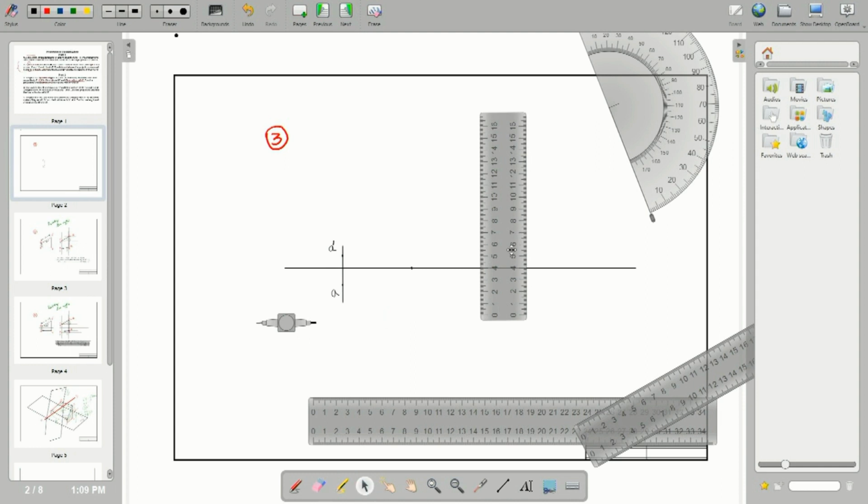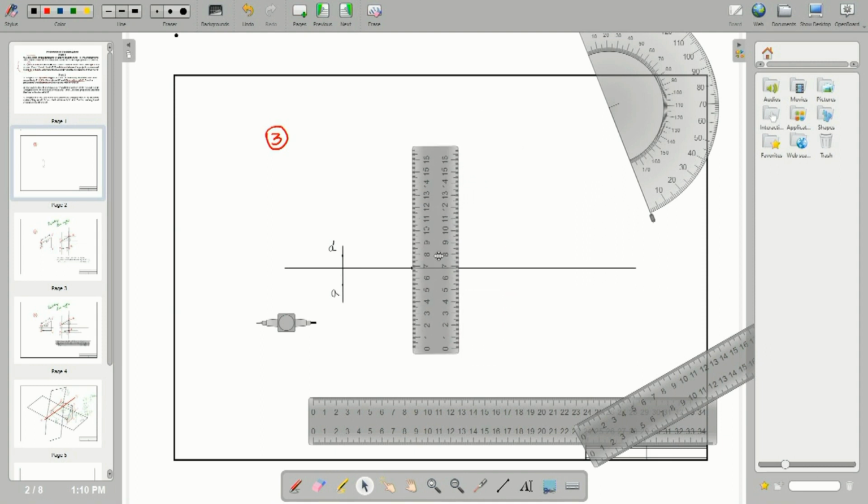By using perpendicular scales, that is in the mini drafter, please go through the mini drafter usage. In that mini drafter, there are two scales, one is a horizontal scale, another one perpendicular to that. You can also make any inclination, with the angular plates at the scale end. By using that you can access multiple applications, without going for any separate rulers. That is the application of the mini drafter. So, with the help of the mini drafter perpendicular scales, we have to draw a projector.